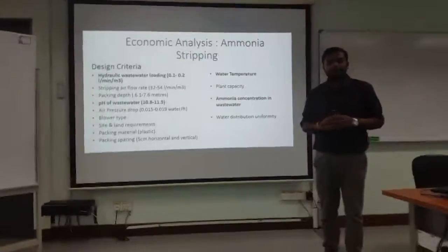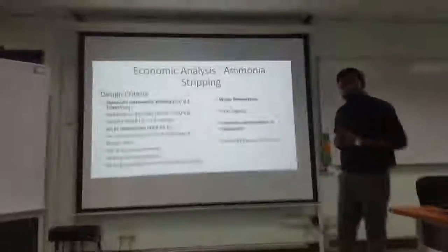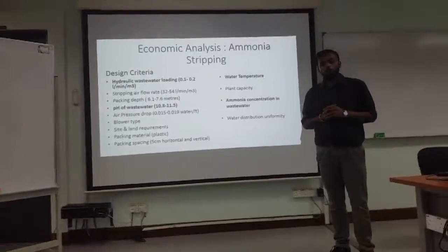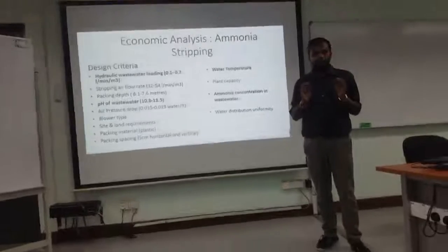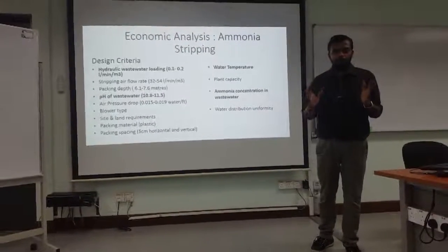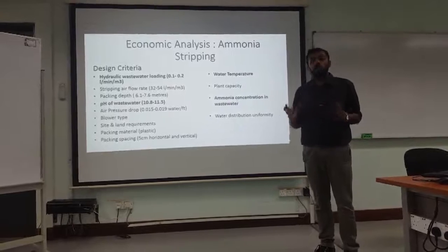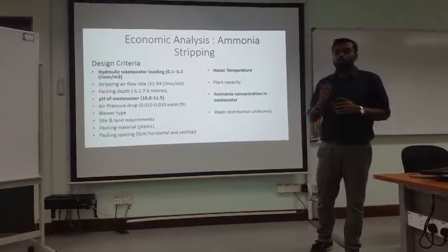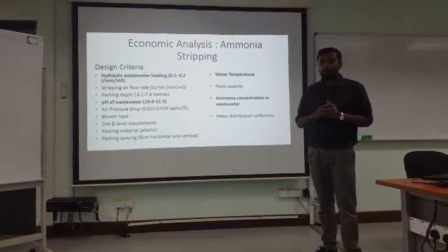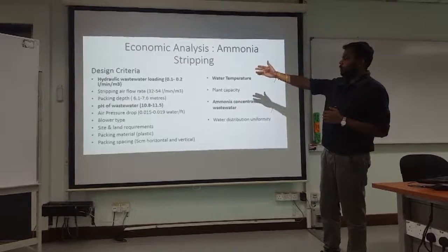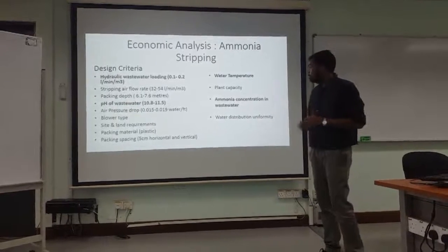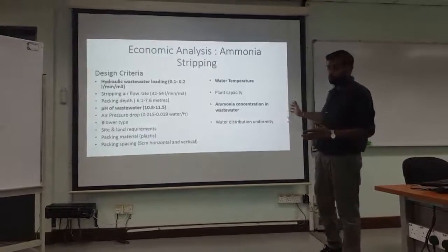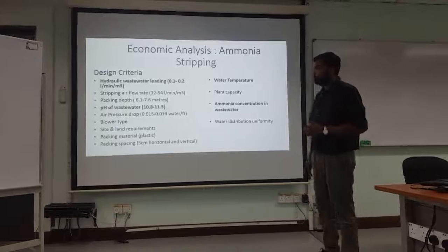Today we are going to talk about the economic analysis of ammonia stripping in industrialization. First of all, to cost an ammonia stripping column, the main criterion is the design of the ammonia stripping column, which will determine the cost of the project. There are three to four important details in costing ammonia stripping: the hydraulic wastewater loading, pH of wastewater, water temperature, and ammonia concentration in wastewater, as I have bolded in all these criteria points.